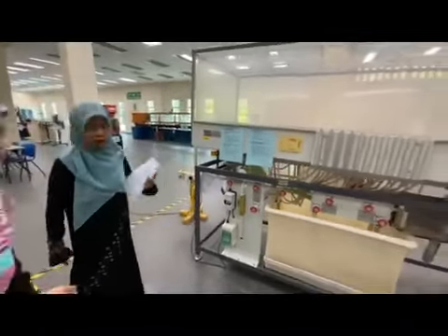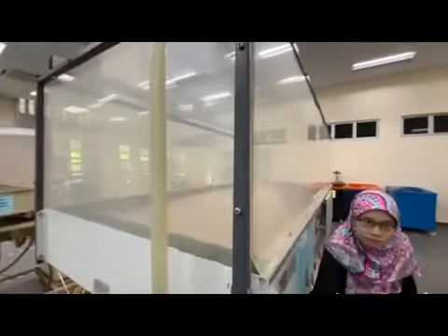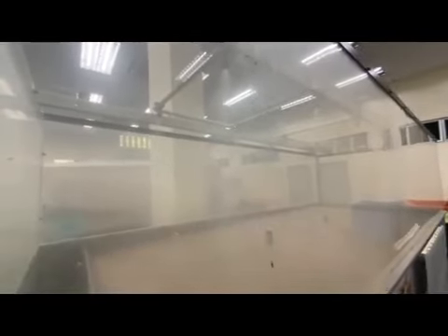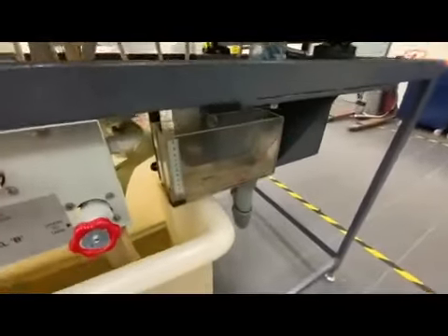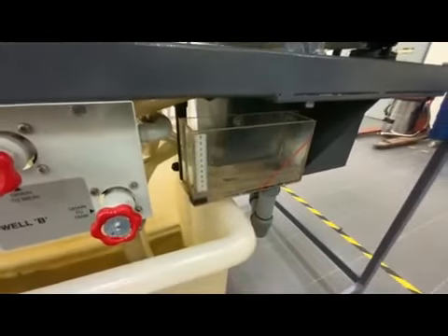Okay, this is on the valve at the upstream. We have 8 valves here, the sprinklers. So we need to open only 4 valves, representing the upstream. And if you see inside, you can see the infiltration or runoff happen inside the catchment area. It will go to the downstream, and later it will infiltrate into the soil and go to the container, where you need to record or measure the water level.